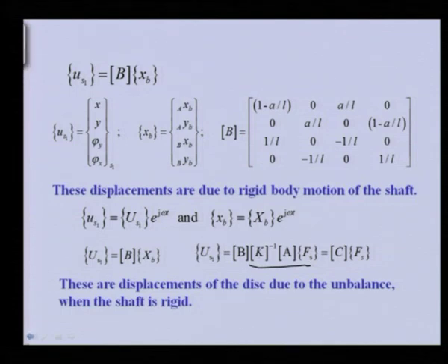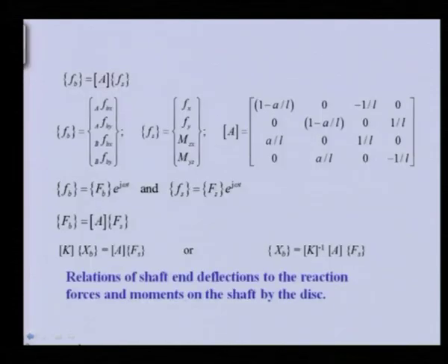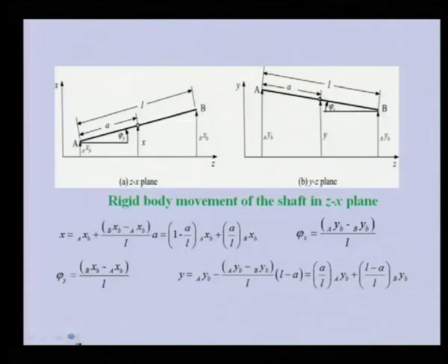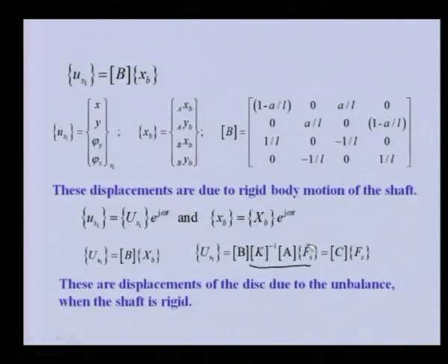If we go back, you can see how we defined x b, we wrote it like this. So, we substitute this in place of x b, and I am defining b my inverse of k and A as C now, and this is the shaft reaction force which is coming from the disc. Now, we will go for the flexibility of the shaft.